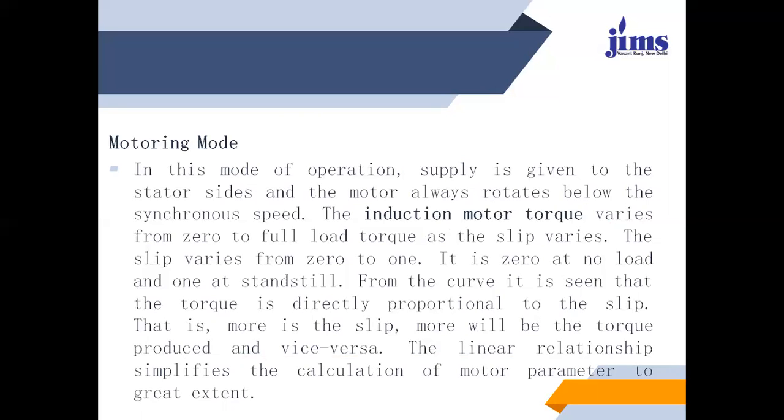From the curve, it is seen that the torque is directly proportional to the slip. That is, the more the slip, the more torque will be produced, and vice versa. The linear relationship simplifies the calculation of motor parameters to a greater extent.